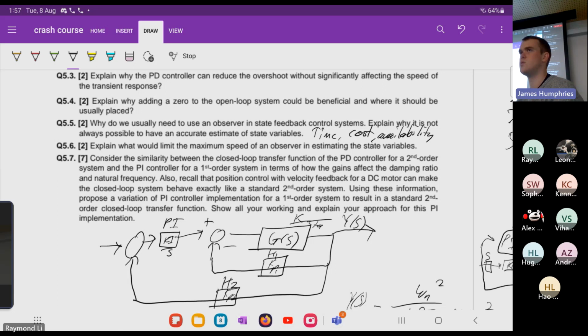I think integrals, like, is that a lead or a lag? I don't remember. I know exactly what you're referring to, and I put it in those notes. I'm gonna go with lag. Yeah, because it would be slower. That would make sense to me, because if you integrate it, you need to take time to accumulate. So if you're worried about steady state, you look at integral control. It takes a while, but it gets rid of all that area. And then your derivative will be advanced and transient. Sweet, thanks. That's intuitive.